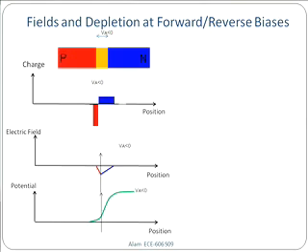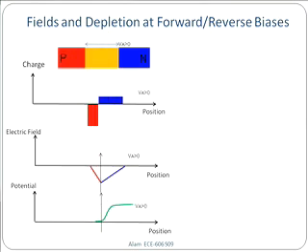And on the reverse bias side, it essentially gets widened out, right? More depletion, and when you have more depletion, what happens? The electric field also goes up. That's very important because we'll see in the reverse bias side, remember the one part where the current was increasing tremendously at a high bias? That is because at high electric field, there will be impact ionization in the diode. And as a result, that's the physics of that part. So we'll do all this a little bit later.